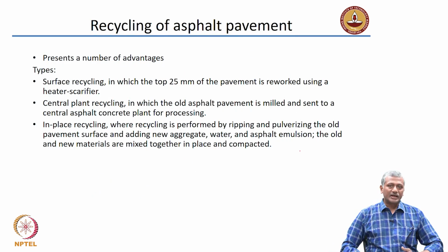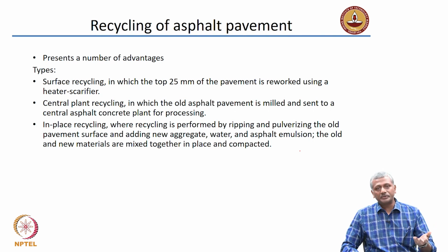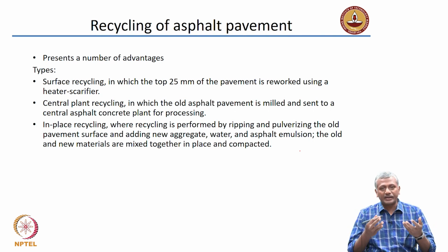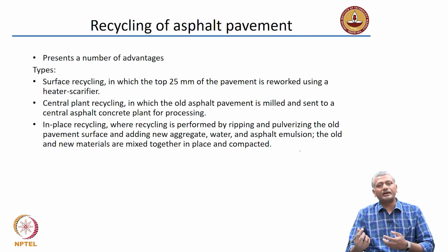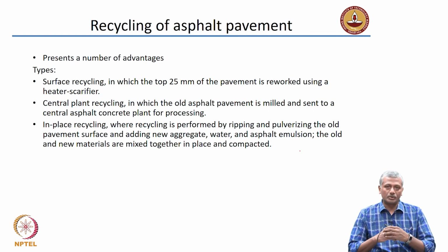Okay, so now we talked about asphalt as a polymer. The fact that asphalt needs to be mixed with the aggregate causes the asphalt to be either heated up to a temperature where it's almost like water, or it's very low viscosity so it can mix with the aggregate, or we make cutback or emulsion and then use that for the production of asphalt concrete.